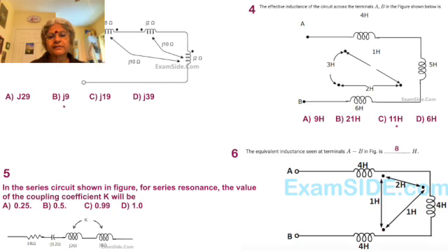So we'll talk in Henry this time, unlike in the earlier case. We have minus 2 Henry as the mutual inductance contribution, and then between 1 and 3 we have 3 Henry, and current enters the dotted and exits the undotted terminal with respect to the two coils. So we have minus 6. And with respect to coil number 2 and 3, it is 2 Henry, so it's 4 Henry. But at the same time, it can be seen that the current exits via the dotted terminals for both the coils. So we are having a plus 4 in this case.